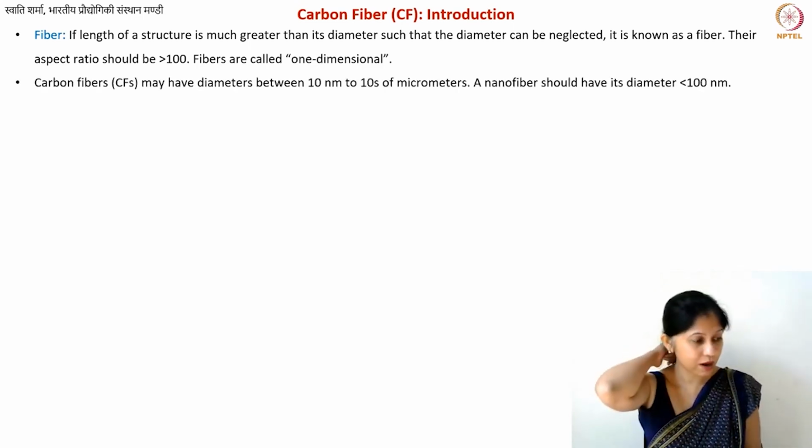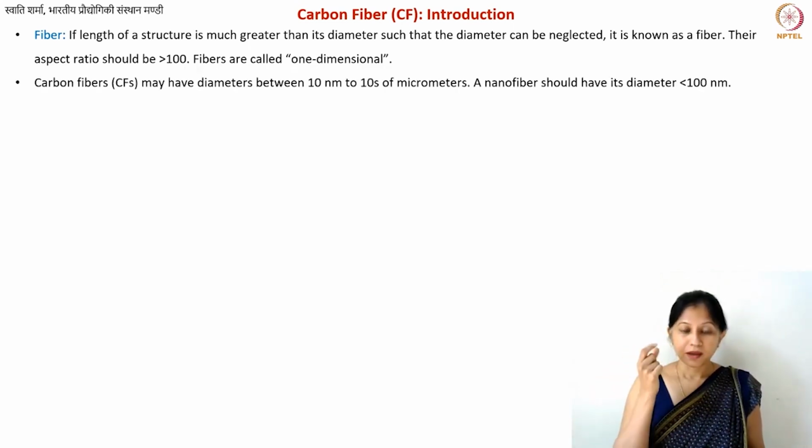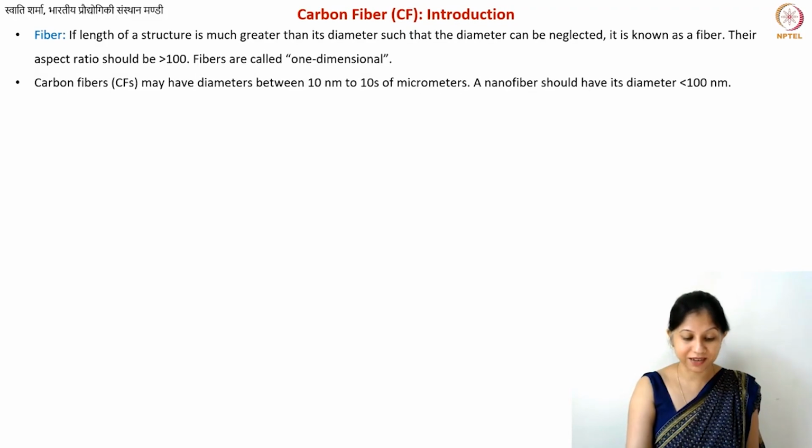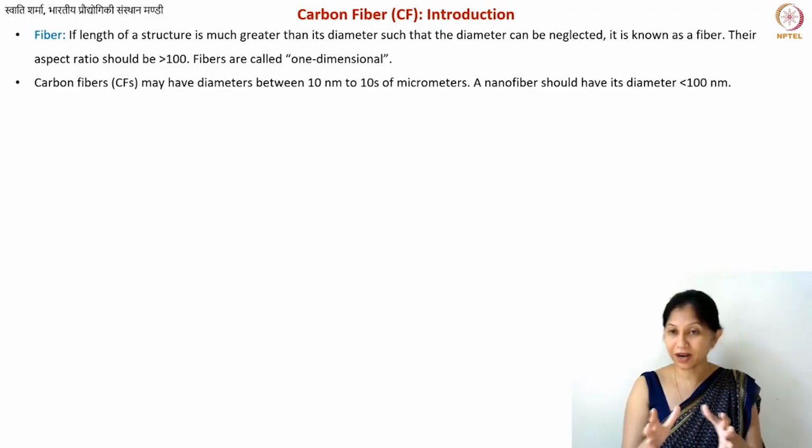But what are carbon fibers? Well, they are fibers from carbon, but you know that carbon is hard and brittle, and you cannot directly pull fibers out of it. So you also know that there is one more method that we use for making industrial graphite structures. We also use it for making industrial bulk glass-like carbon materials. We shape the polymer and then we carbonize it. We do the heat treatment.